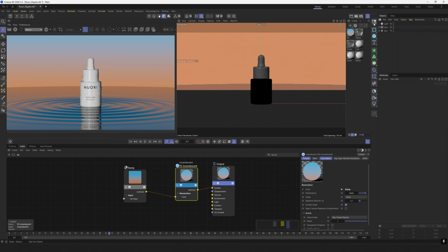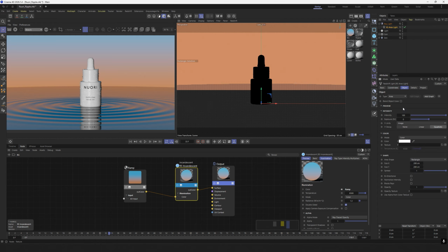Now let's add lighting. Create the main light, K-light. Create null, named K-light, and add an area light. Open its settings, set a low intensity value of 1. Set the size to 50 on X and 20 on Y and reduce spread to 0.3.